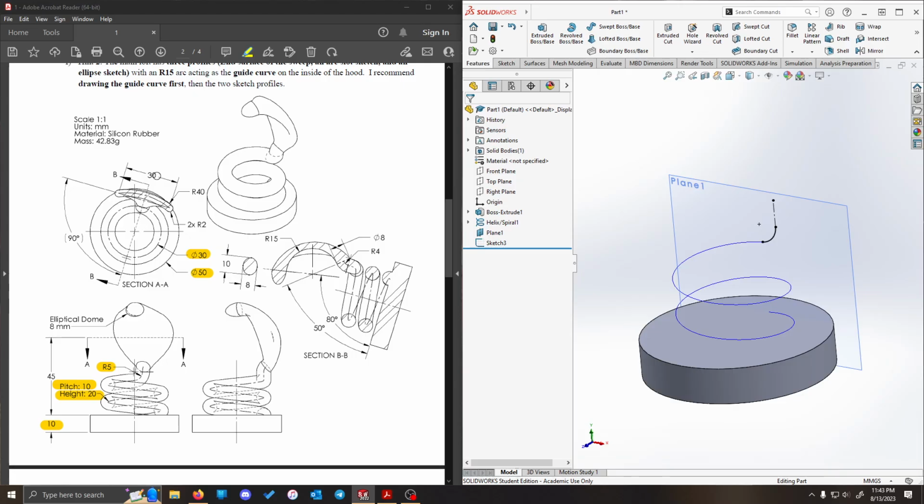well, the entire plane shows up as a line in our top view. So we could use that to say, oh, well, this plane is also perpendicular to the top face of our object, or the top plane. Or if we wanted to be slightly more efficient, we can also notice that because the plane goes through the middle of the circle, that tells us that the plane itself is going to need to be coincident with the center line of our cylinder.